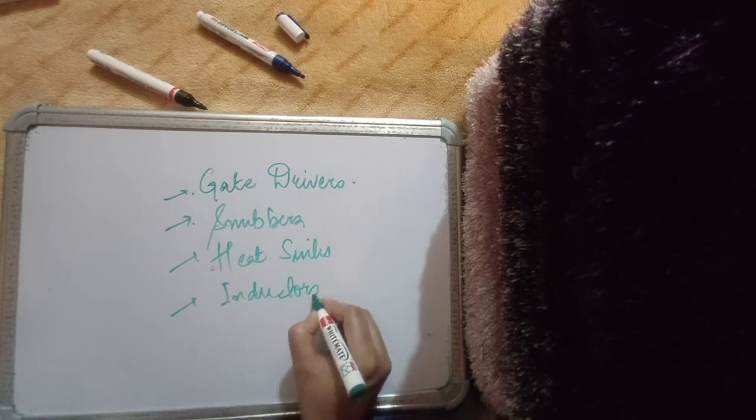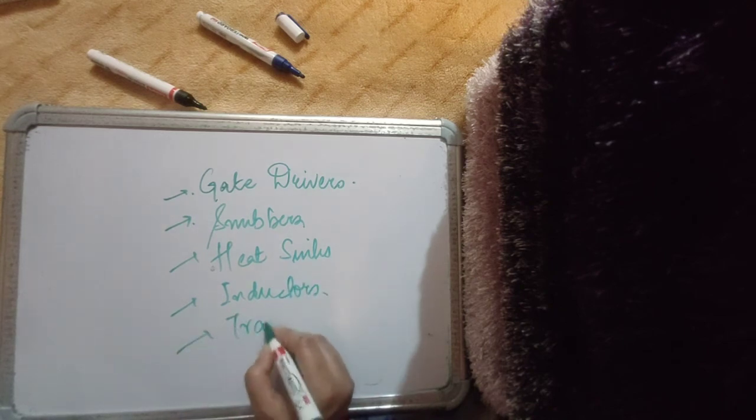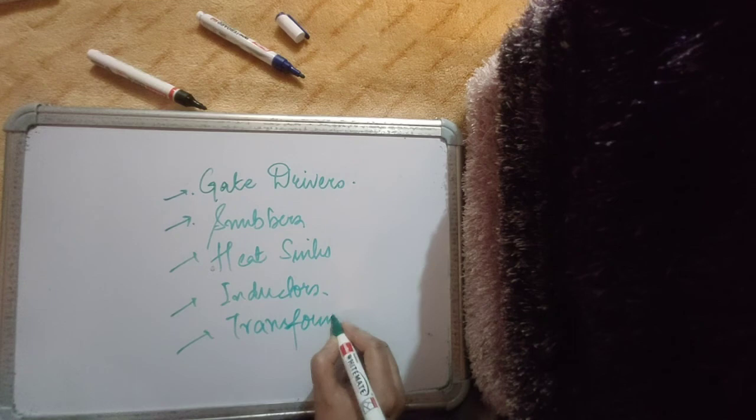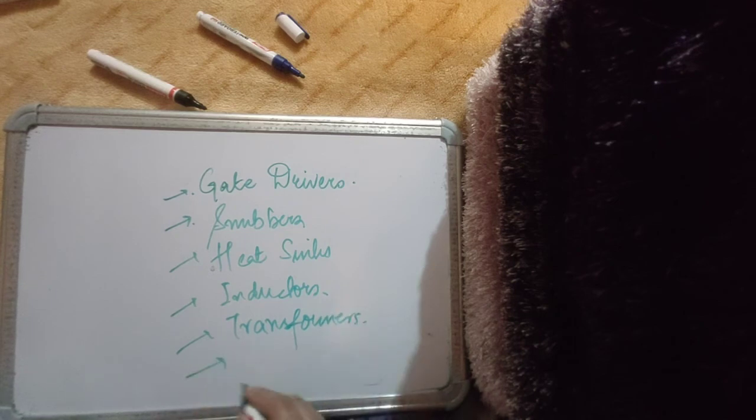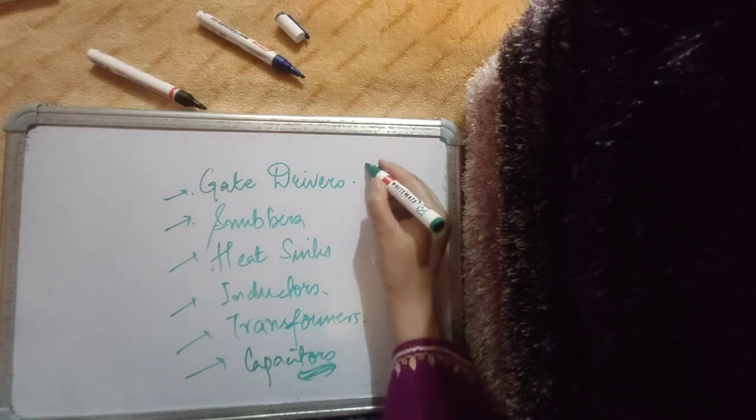Very similar to inductor design has been design of transformers, and lastly we have briefly discussed the design of capacitors, especially DC link capacitors, which are not only designed to minimize the DC link voltage ripple, but also to provide some fault ride through capability, sustaining the load for a few cycles of interruption in the supply. So all of these we have discussed.